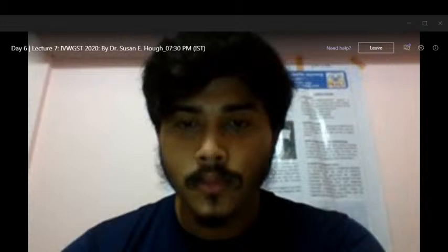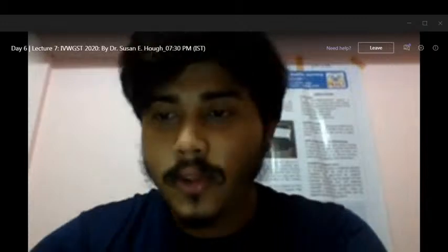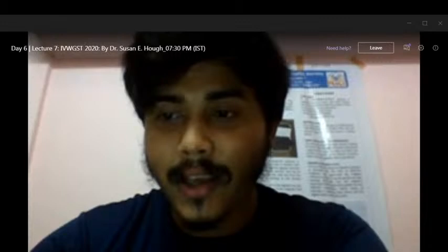Tashina Alam wants to know, Dhaka city has areas where rivers and ponds are filled and then constructed upon. What type of site responses can we expect there? I didn't hear the first part. Can you say again? Dhaka city has areas where rivers and ponds are filled and then constructed upon. What type of site response can we expect there? Is the question about artificial fill, places that are filled? Yeah, that typically gives rise to strong amplification as well.